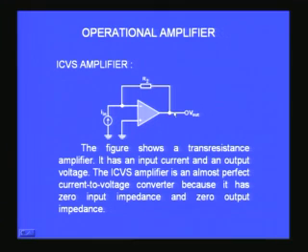All that we have done is connect the output high point to the input high point through a resistor R2, which is the feedback network. The feedback network is a single resistor, and the entire voltage is connected back here. Therefore you can immediately imagine that the feedback ratio, the fraction beta, is 1 in this case, because the entire voltage is given at the input.